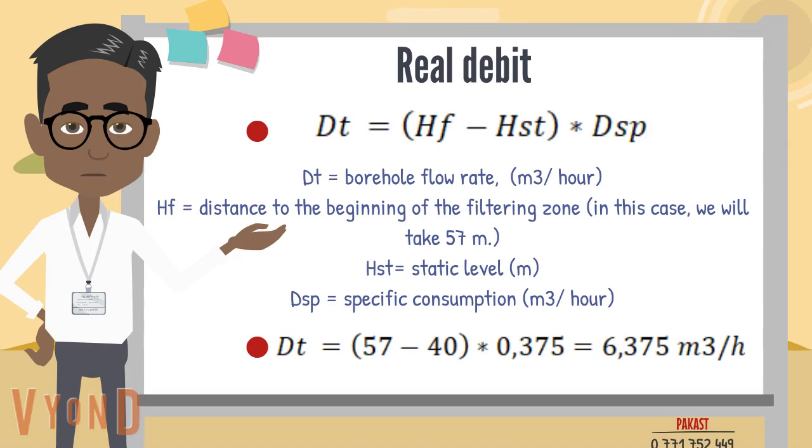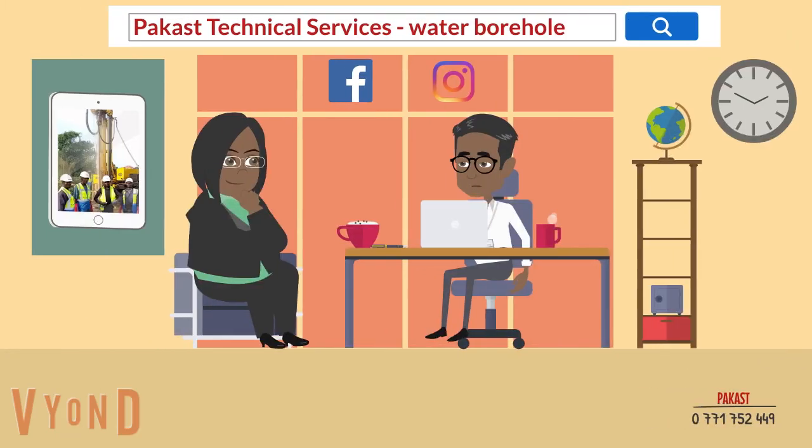As you can see, in the case of our imaginary well, the difference between the simplified and the subsequent measurement is almost 2.2 cubic meters per hour in the direction of decreasing productivity. The borehole flow rate is calculated at the stage of determining the depth of the water pumping aquifer, drawing up the design of the well, choosing the type and brand of pumping equipment.